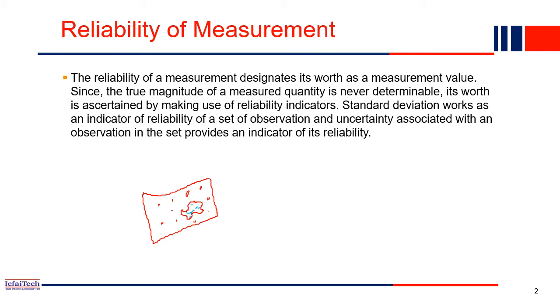In that case, what you have to do is take the measurements, right? From each control point, for this control point, what is the distance here, and how much angle does it make with the vertical? This is our north direction of this plan. How much angle does it make, and also what is the distance from this control point. Similarly, from this control point, what is the distance, and what is the angle with the north. Similarly, for this point, what is this distance, and how much angle does it make with the north.